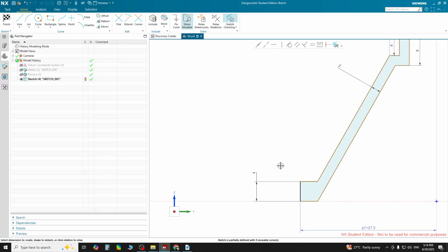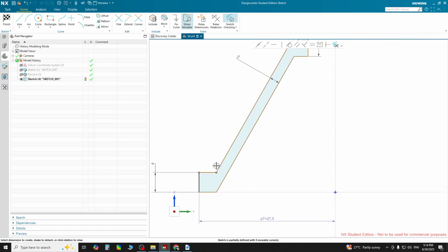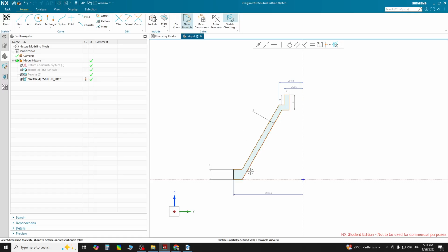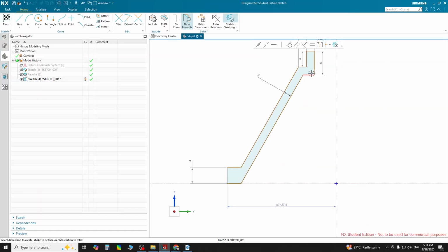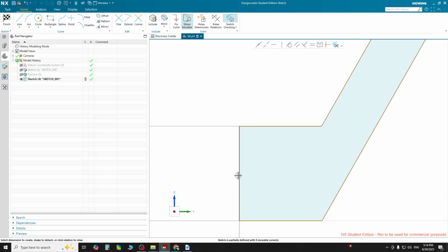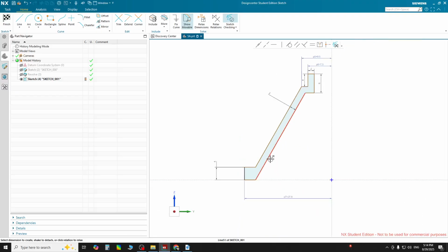When placing the dimensions one by one, in some cases the figure takes a very bad shape, then you adjust the shape by stretching the other portion. Which ones can we stretch here? Only those in little yellow color. Those that become black are already in defined mode, so we cannot move these black sketches. Those that are not defined, in yellow color, we can stretch and adjust.